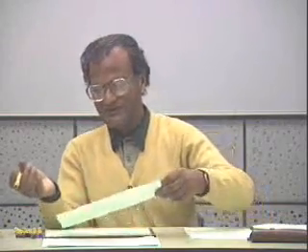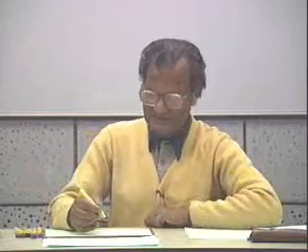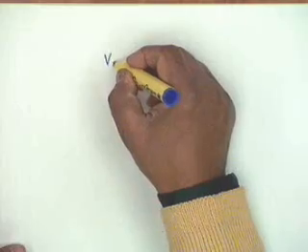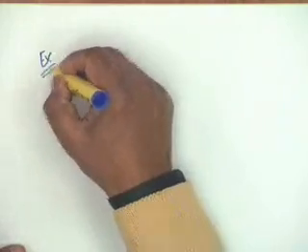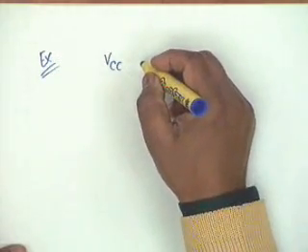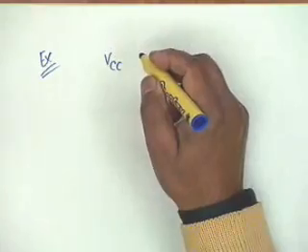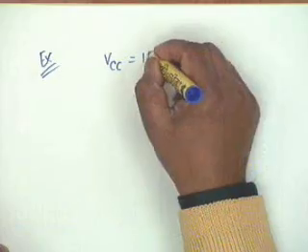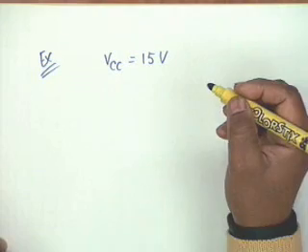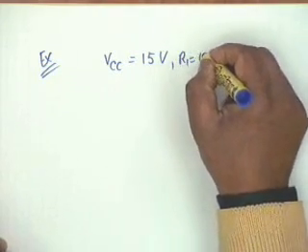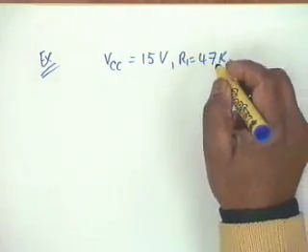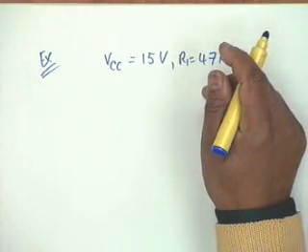But in class AB, naturally, because you have to tolerate an amount of quiescent dissipation, the efficiency will go down. We will calculate efficiencies later, but let us look at an example. Suppose in this class AB circuit, VCC is plus 15, minus VCC is minus 15. Suppose VCC is 15 volt and R1 is 47K. R1 is that reference resistor for the current mirror.